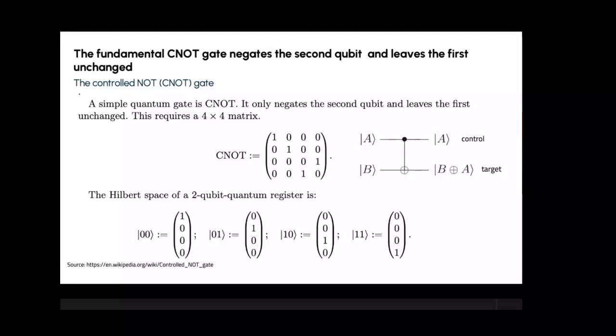So let me show you what that means. If I have here A and B and then XOR, we have looked at it yesterday. I can have 0, 0, 1, 1 here, and then 0, 1, 0, 1 here. I think this gives me all 4 combinations. So in an exclusive OR gate, this is the result.